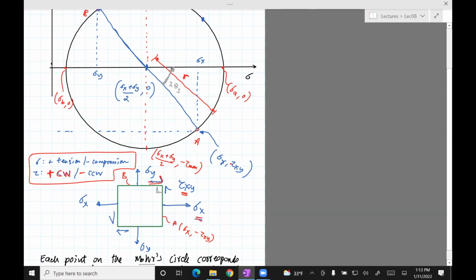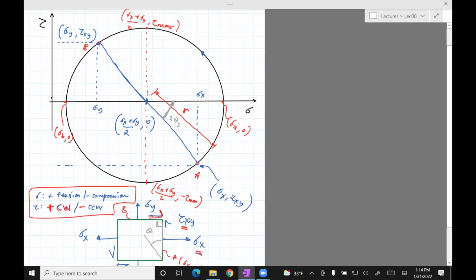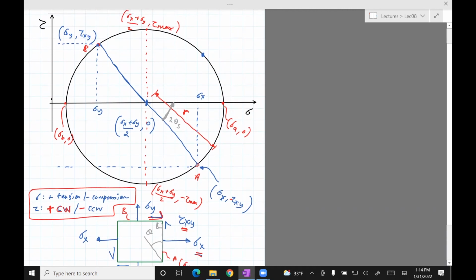So you need to turn this face by an angle of theta, so something like this. That direction is the direction of principal stress sigma A. Okay, and then if you want to find the angle at which there's a maximum shear stress, then it's basically this angle. Goes from here all the way to there. And that was also a derivation.